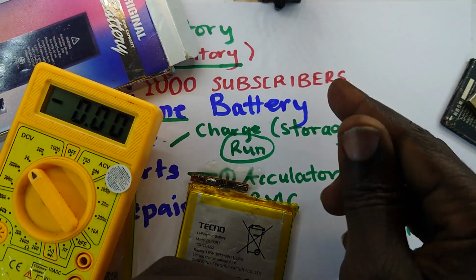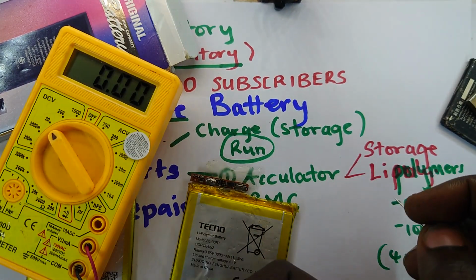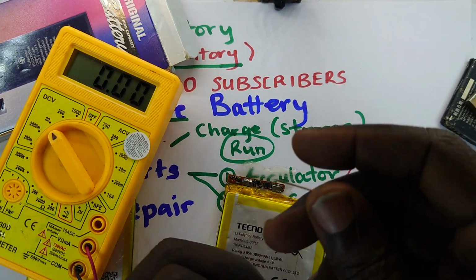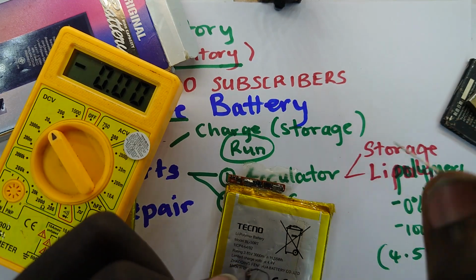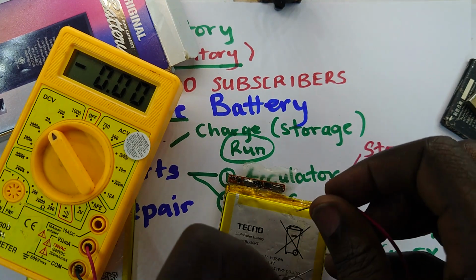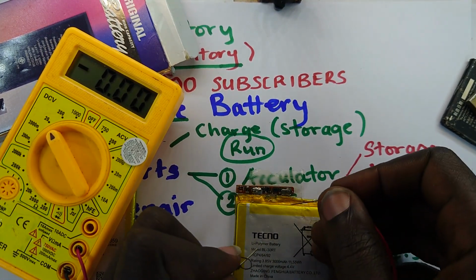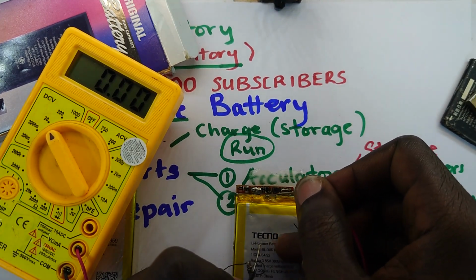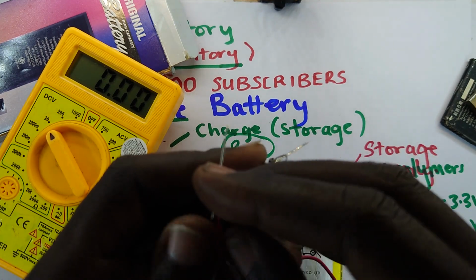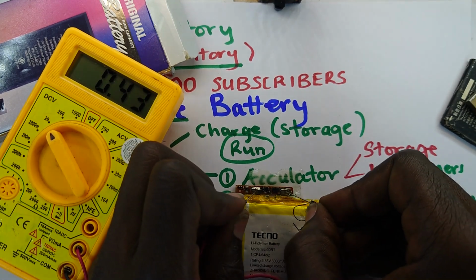Now this red is the positive probe of my multimeter, and this black is the negative probe. So when I get a positive value, that means I've put the positive probe on the positive terminal of the battery, and the negative accordingly. If it is negative, that means it's reversed. That also helps you tell which terminal is positive and which is negative. If you're lucky and the battery management board is still attached, normally negative and positive are indicated right there. So I'm going to do this because that's what's written, and put this over the terminals.